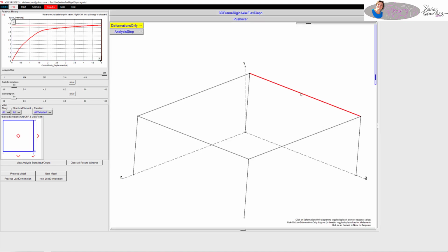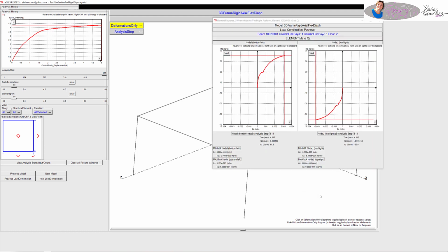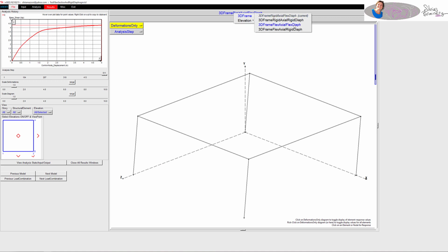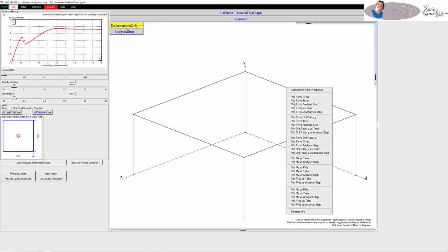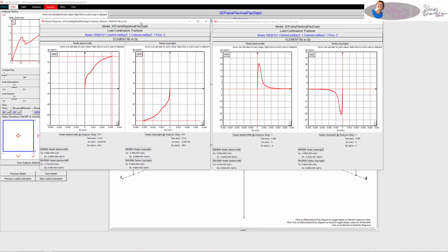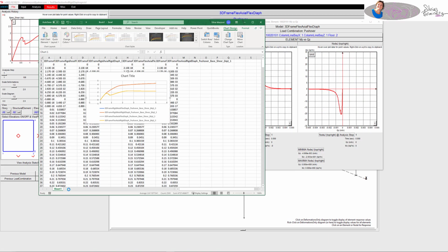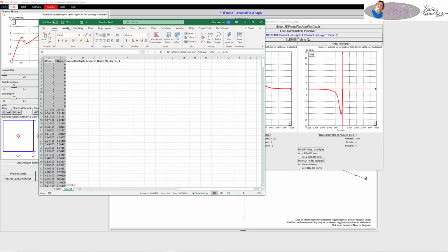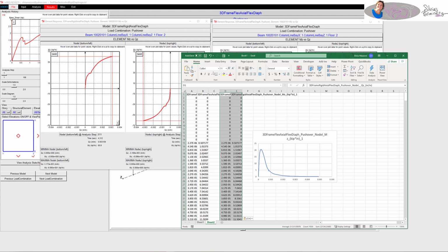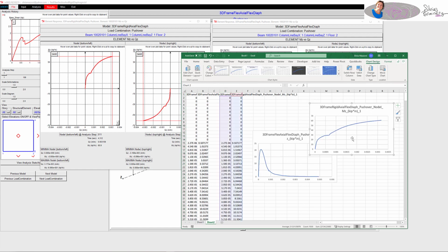What I'm going to do now is show you the moment rotation or moment curvature results for each one of these cases. And you'll see that the moment capacity when you have PM interaction goes up. And also remember, because we're pushing over and because of overturning, the axial force is increasing in this beam as well. And I will show you the plot there because we're going to want to look at the axial force. But so now if we compare these two strengths, first I'm plotting the capacity, the moment curvature response of the one with PM interaction and the one without PM interaction.